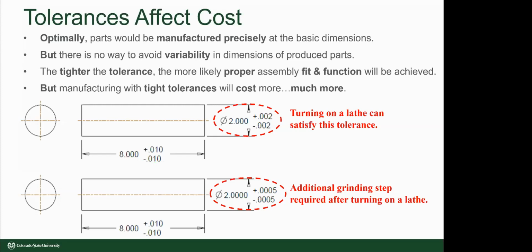The increased cost stems from more time needed to machine to that tighter precision, and different machining operations needed to achieve that tighter tolerance, because as you request tighter and tighter tolerances, there might need to be additional machining operations to achieve it. And all that takes more time. Plus, the reject rate when you're doing your quality inspection of the part might increase. You might have to reject more parts because meeting tighter tolerances is less likely to occur on average.